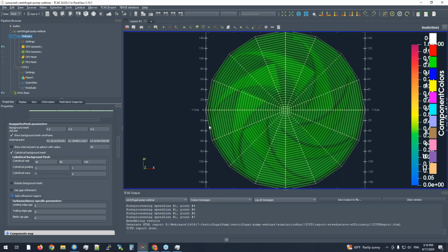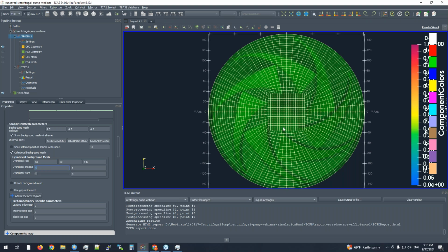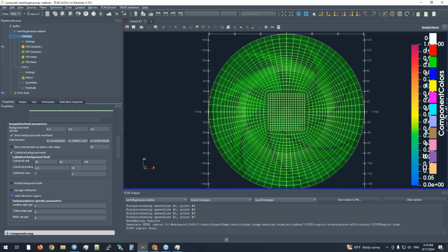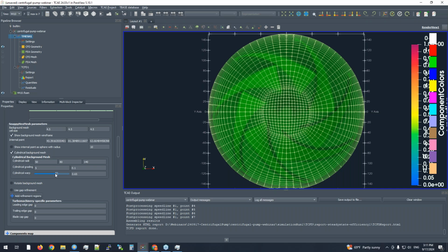You can do it in this way, but then you have really thin, not nice cells in this area. Right. So if you enlarge it, then this unsymmetrical part can go into your symmetrical part. In general, I would say this cylindrical background mesh intuitively looks good because it's aligned with the rotating speed, right? It's quite aligned with the rotation. So intuitively it should be good, but it definitely deserves to be tested more. And yeah. Let's finish here because we don't really have any conclusions here.